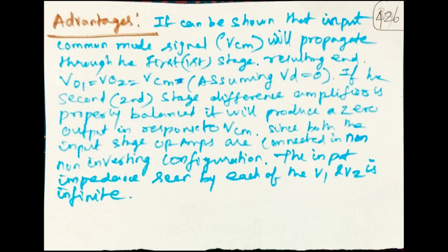It does not respond to VCM. Since both the input stage op amps are connected in non-inverting configuration, the input impedance seen by each of V1 and V2 is infinite.